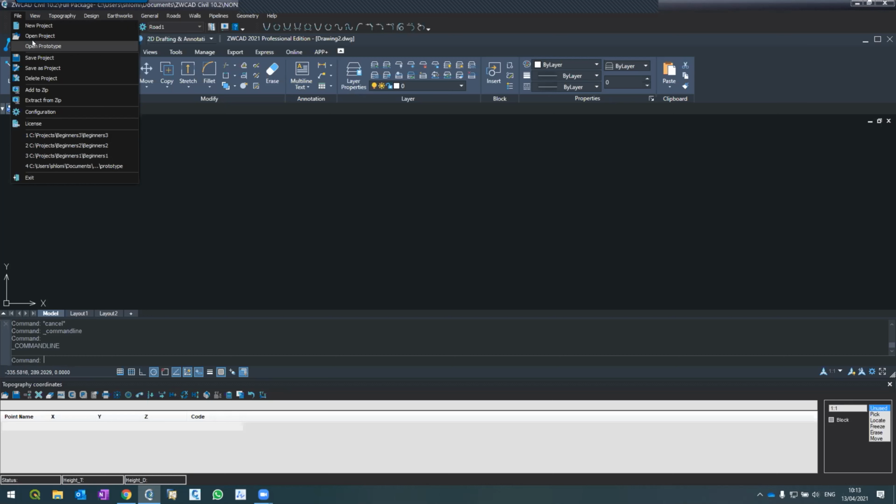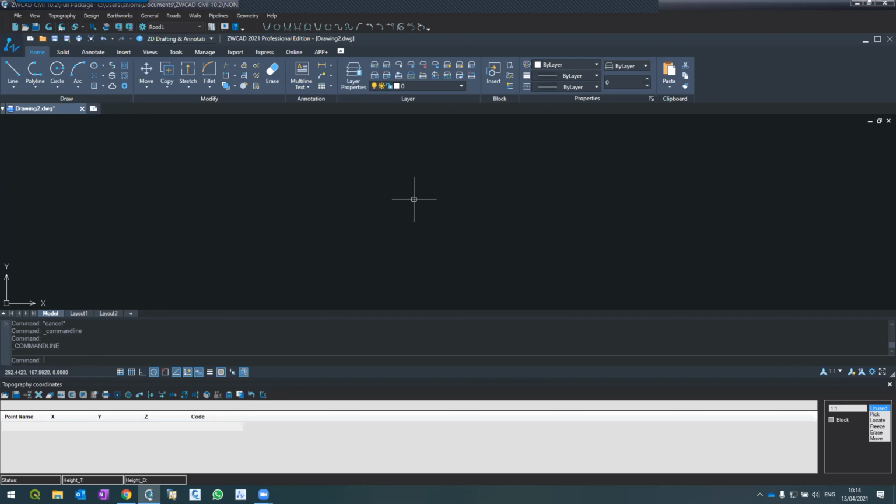And we learned how to set something that we call global scale, which is the text height or the text size, adjusted to a certain printing scale. And we learned how to choose which ZWCAD drawing environment we use. For example, if we have two ZWCAD versions in our system, one is 2020 and one is 2021, we can choose which one we want ZWCAD Civil to work with.